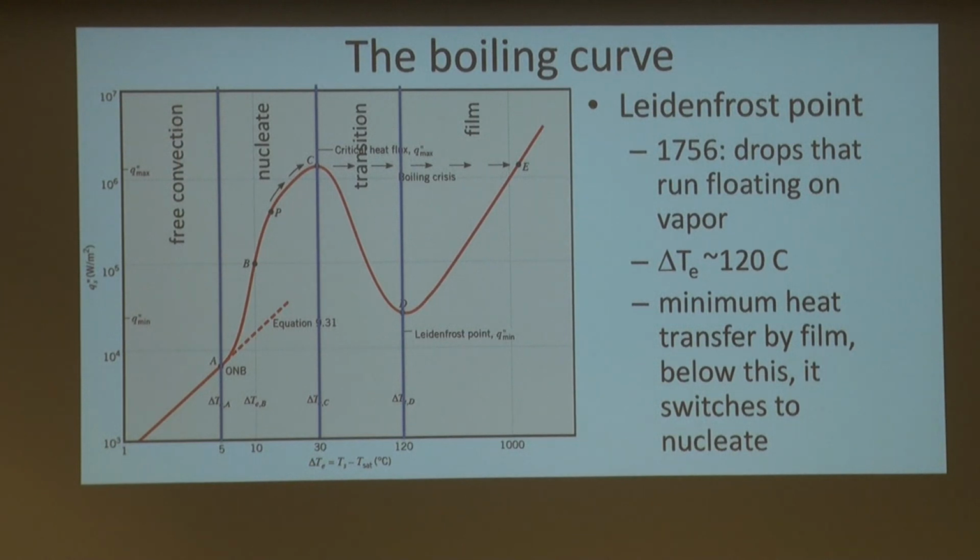What happens at that point is you generate a very thin film, right? And vapor has very low thermal conductivity compared with liquids, right? So this little film between the surface and the liquid creates an insulating layer. In this aspect, it's very similar to a boundary layer, right? When I mentioned between my arm and the air surrounding me, there is an invisible layer of stagnant air, through which we have conduction, and this is insulating. In that case, between the solid and the liquid, we have a thin layer of vapor that is acting as a boundary layer.